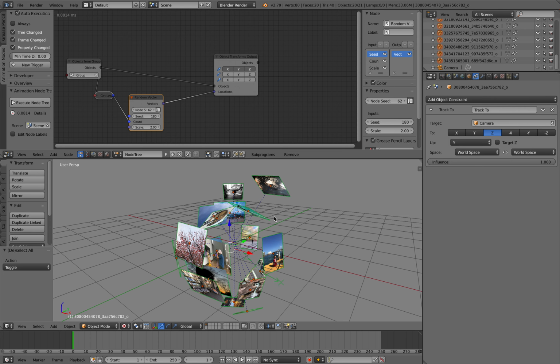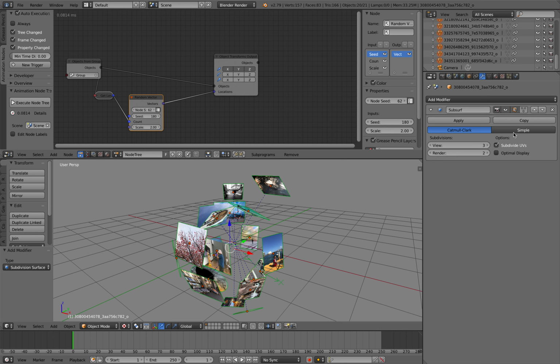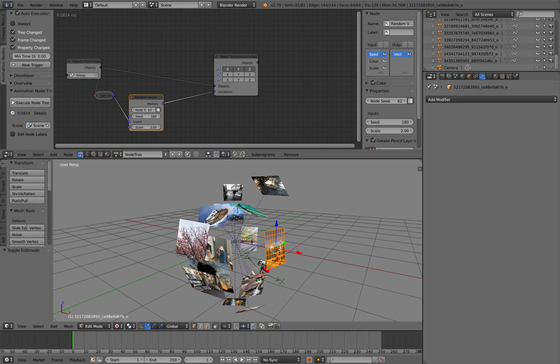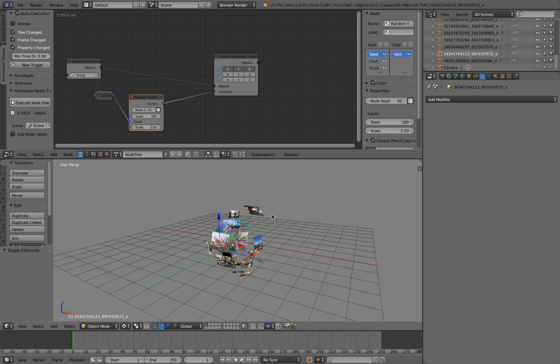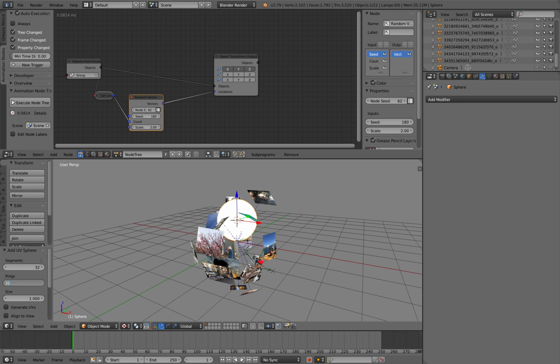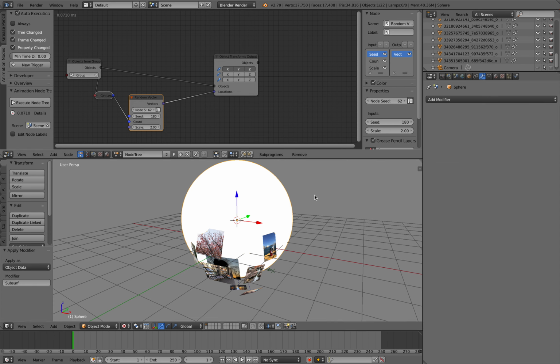So with all of them selected, I'm gonna simplify a couple of times with simple, and then Control L, copy the modifier, and then just simply apply, convert to mesh. So they all now have a little bit of detail, so we can project it into a sphere. So hopefully this works. Hopefully, fingers crossed. I didn't actually try this beforehand. So sphere, sphere, sphere. Make it 32 by 32. Like, I think 32 is good. Generate UV, subdivide it, apply, and this guy should just be like a wire.